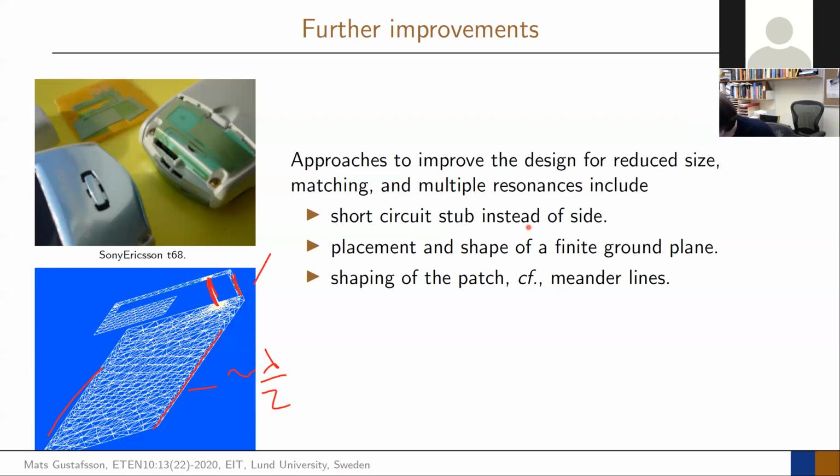And what you can see up here, which come back to these ones, are typically these patches. These are modified to have dual resonances, because in this kind of phone, you need a 900 band and an 1900 band. So you need 2 resonances on the same patch. Nowadays, you need many more. And you can change them then cutting away pieces here. So in these cases, you have one dimension there, and you have a longer dimension there. The longer the dimension, the lower the frequency.